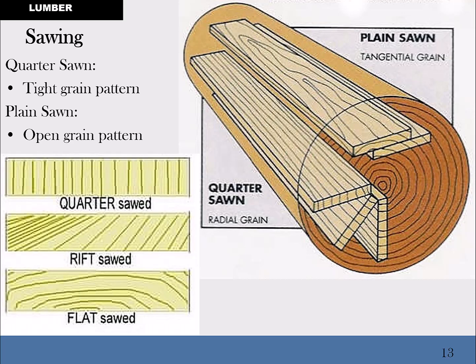And so when we're building furniture, stuff that's going to be seen, if it's going to be painted, no one cares. But if it's going to be seen because it's stained, as furniture, then that grain matters as far as the look, just for the stain. It looks entirely different when you look at the plain sawn. In fact, if you put those two pieces together in the same piece of furniture and stain them, they'll tend to look like they're totally different species that have nothing to do with each other, even though they came from the same tree. So that rift sawn thing is kind of a combination thing.